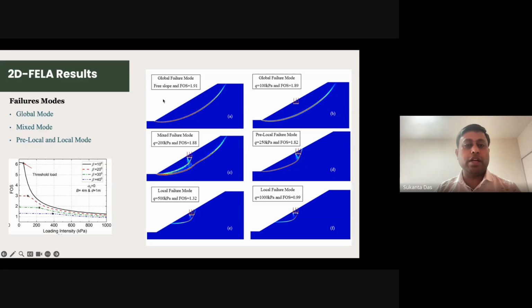So before explaining the other figures, let me take the first figure, when you have a slope consisting of homogeneous soil and a single-phase slope. So what is the expected failure? I hope you all know that it is most likely to fail in a toe failure. Before that, in slope stability problems, you have different slip surface failures. When you have some very soft soil in the top layer, then the slope can fail through the face of the slope.